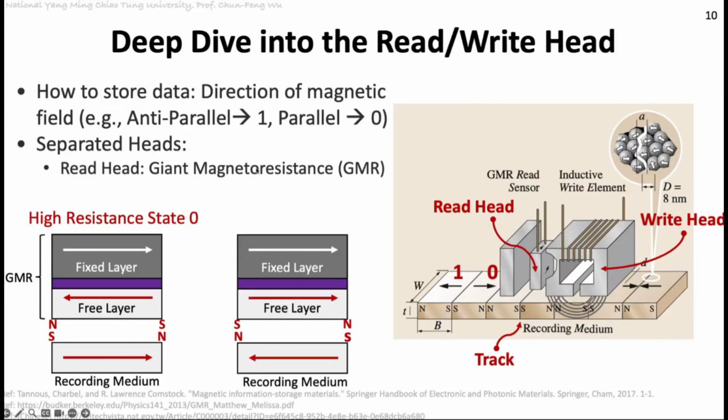Then this GMR shows a low resistance value. Again, because the GMR is always powered on, it gets the same voltage value, but because this is a low resistance, the GMR will return a higher current than the left-hand side.